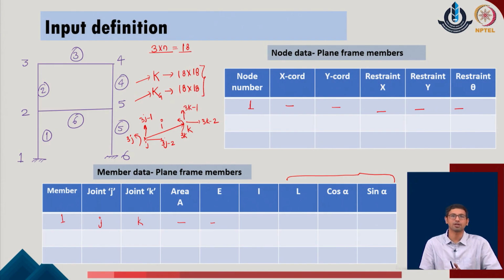So, I think this is what we have done already in the previous system. I can now make a vector containing these 6 degrees of freedom positions, and I can specify that the individual member's linear stiffness, say for the member I, which is already defined in the global coordinates, will go to the specific positions of these particular degrees of freedom in the overall k matrix of the system.